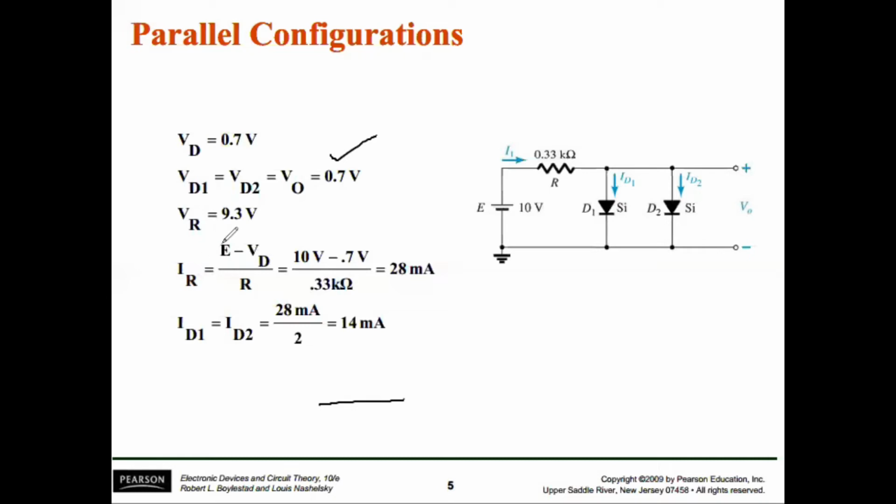What is the value of VR? How can you calculate the value of VR? Just by applying KVL here. If you apply KVL here, it will be equal to E equals VR plus VD.